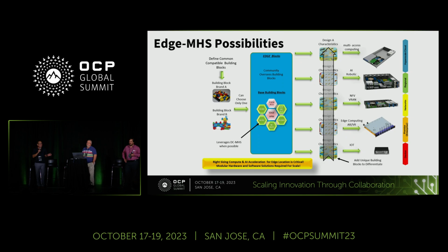And at the same time, we also recognize the DC-SCM module is co-planar today. It definitely goes against the chassis depth design principle. So we're not just looking at the HPM, but we also look at the component ecosystem of DC-SCM so that we can vertically plug it into the HPM rather than co-planar.